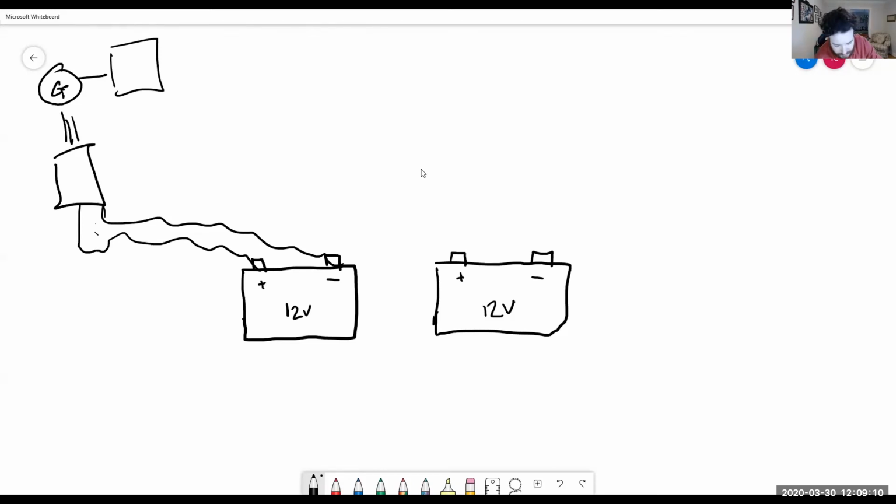But Sundays at sea, thirds usually go out and do their battery checks, which means you go out to all the batteries on board the vessel with a clipboard and an Excel sheet that you printed out, and you write down all the voltages from all the batteries to check if they've gone bad. Because remember, if these go bad, we can't start our engines. So the first thing is your generators are running, because you want to have power, so they're sending power to your rectifier.